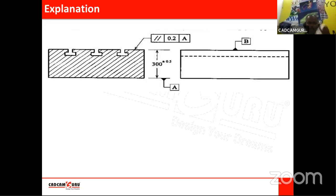And again, here we are talking about parallelism, and error in parallelism is considered by this geometrical tolerance also, the geometrical deviation. So this one is bilateral tolerance, generally not that important, and it is converted into basic dimension. But it is shown here because geometrical tolerance or permissible deviation should be less than dimensional tolerance. That's why I told you about this.